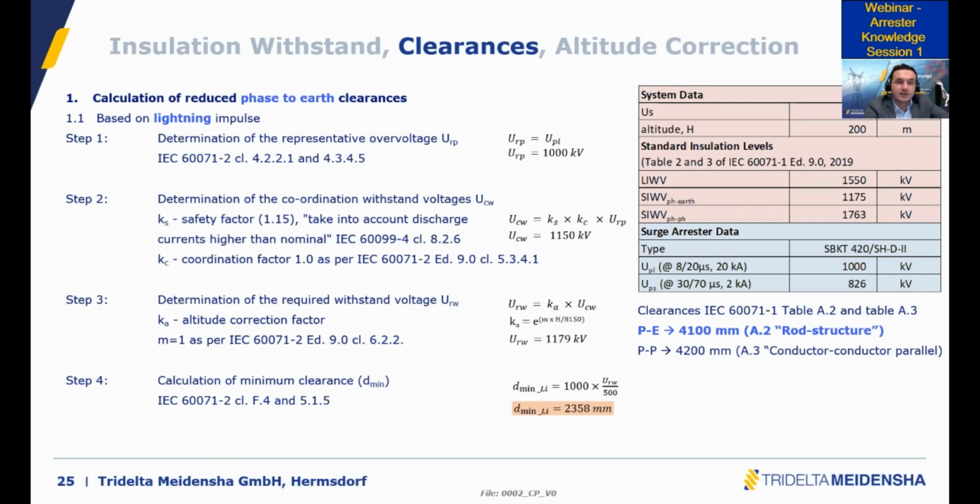Thinking that maybe I need a lower residual voltage. Yes. So the wording nominal voltage is not correct. If we talk about 420 and 396 kV for a system of 550 kV, we are talking about rated voltage.